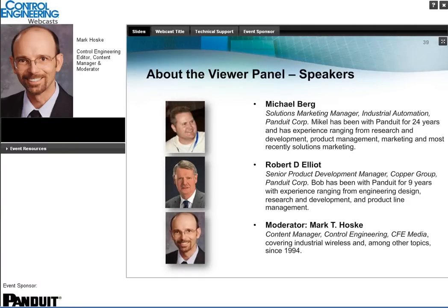That can come at several levels, because it depends whether it means to take into account the performance of the active equipment, when of course you're concerned with aspects such as bit error rate that relate to frame error rate. And the issue with bit error rates is, especially with motion control equipment, some of the manufacturers that we're partners with, if it receives about 3 consecutive frame errors, then that industrial equipment will actually shut down.